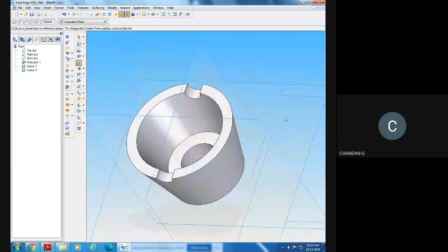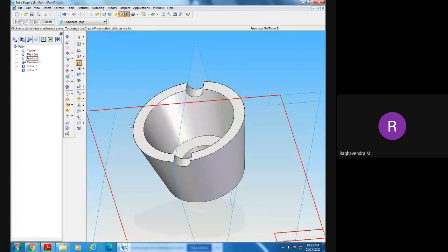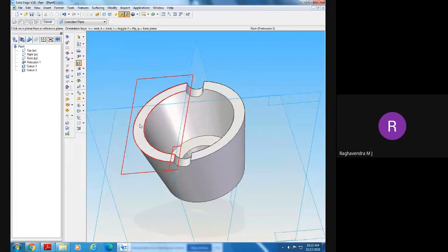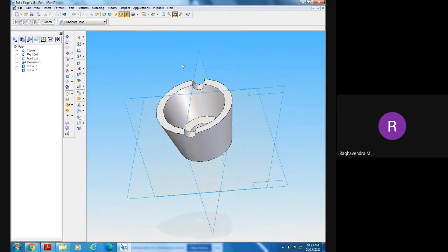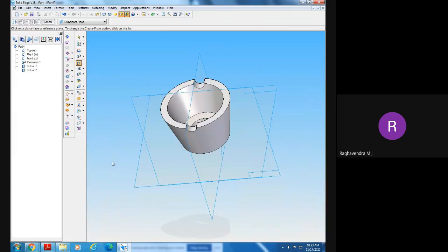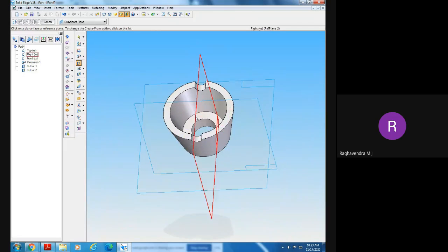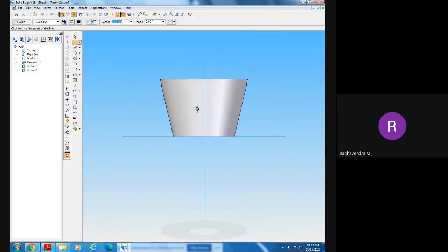Yes, sir. Okay. Once again, we need this direction, a 90-degree direction like this. Once again, 2 cutouts like this. It will come at 90 degrees. Okay, now once again go to cutout. Okay, we have this plane now. Then select this plane. Once again, go to circle. Select the center point. Once again, diameter is how much? 5. Radius means diameter is 10.